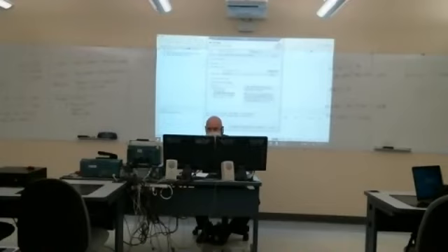And then for the target, mine already has it here because I've run this before. It says MSP432P401R, which is our microcontroller, right? So you've got a list of other ones there, but you want to make sure that you select the right one. And then I'm going to call this hello 2. I've already got a hello world. Okay. And then the project name.